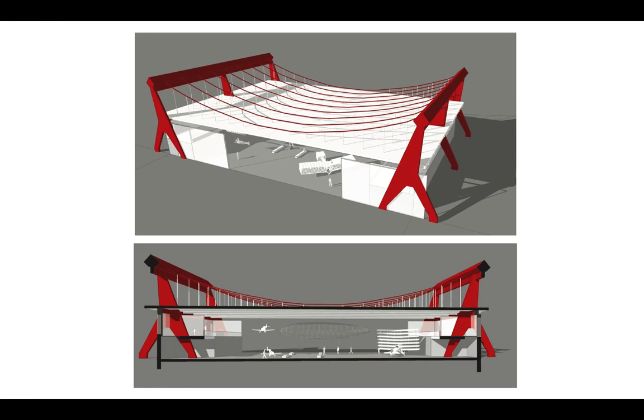First, you might remember that when we were talking about suspension structures, we talked about being worried about uplift, right? That these structures are so light that we have to accommodate not only the gravity loads and the wind loads or lateral loads that we're used to accommodating, but we also have to worry about the possibility of the wind actually sort of spilling over a flat roof like this and literally lifting the roof up. And we had talked about a couple of ways that we use cable structures to absorb not only gravity loads, but also these uplift loads.